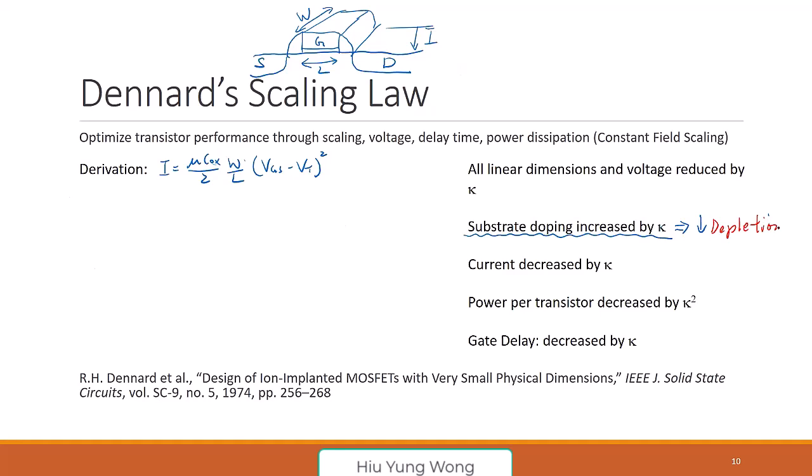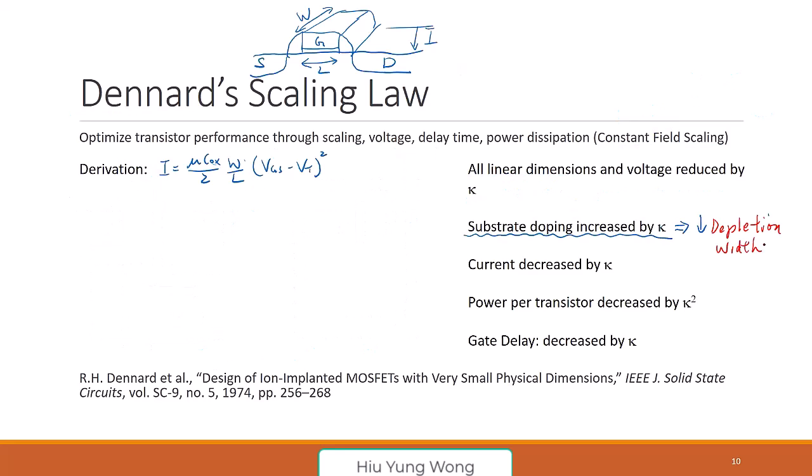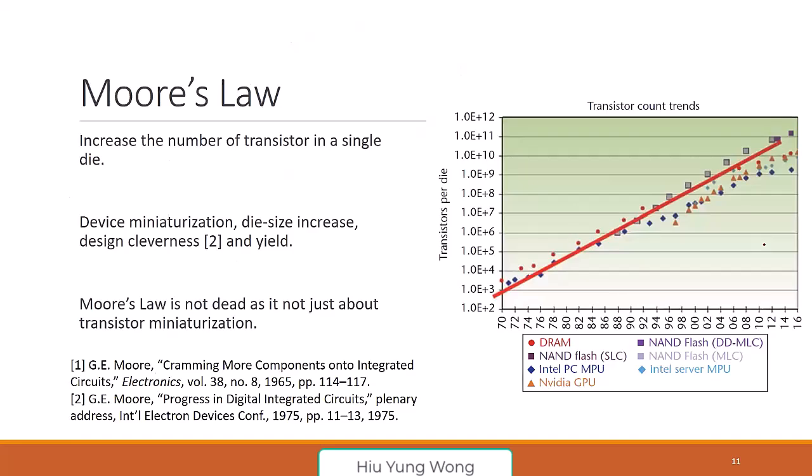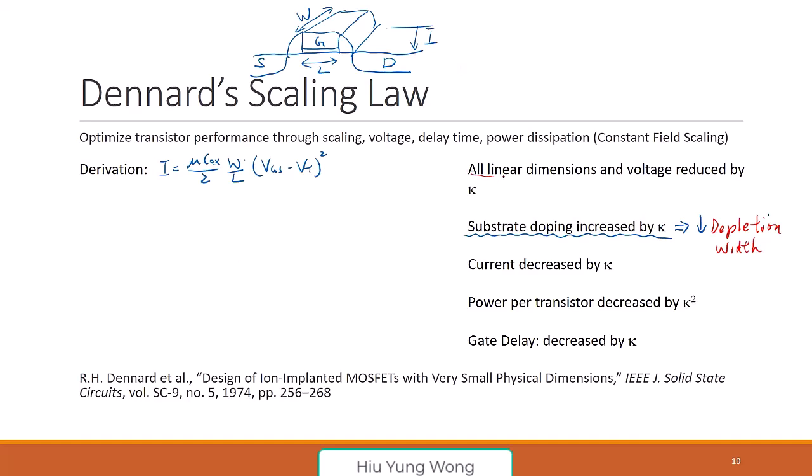Okay, thank you. Now, the reason we want to scale the substrate is to reduce the depletion width. Remember, Dennard said that I want to scale all linear dimensions.